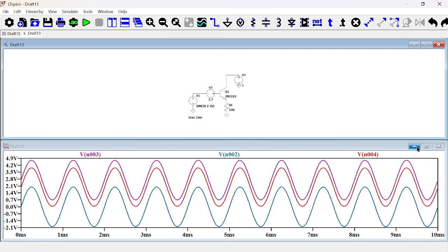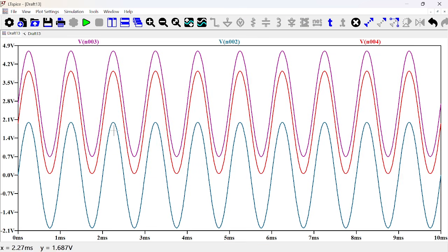So you've seen the major drawback. We need a huge biasing voltage. That means a huge current should be flowing through this always, which is not good. Especially as the voltage rises, we need more bias voltage, more current, and that is not good. So there's a better way of doing that, and that's called the push-pull stage.